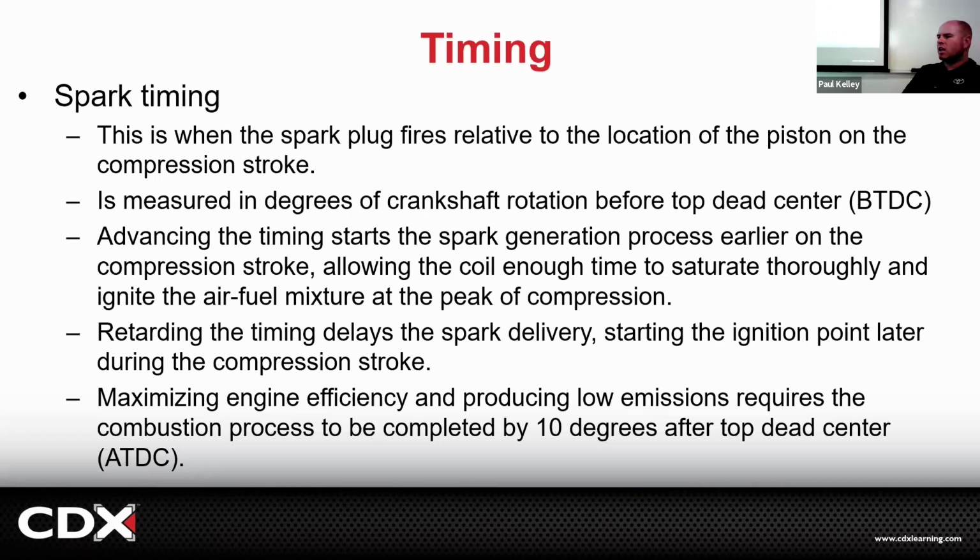So if you over advance your timing, you can damage your engine, especially the rod bearings, because the crankshaft's pushing the rod up. The early combustion pushes the piston down, which pushes the rod down, and your poor little rod bearings are like, pow, pow, take that. Again, every revolution it gets punched in the face.